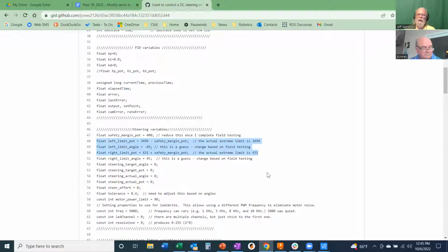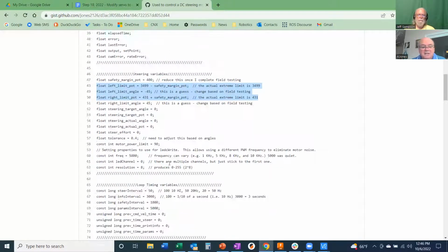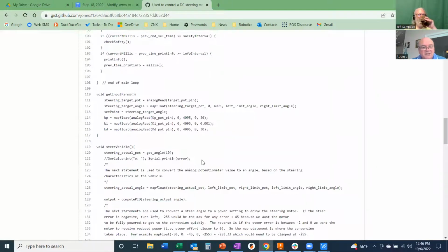First of all, just look at the pots without any averaging, all 5 pots, and see if any of them are noisy without doing anything. Then I assume once the motor starts moving, the steering pot will become noisy, and that's why you originally had averaging stuck on that. I originally had averaging stuck on there because the guy who wrote the example had averaging in his example.